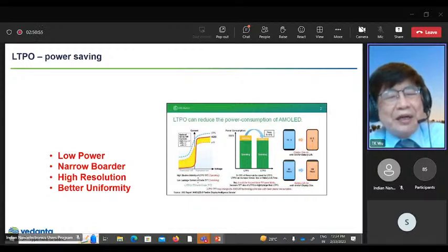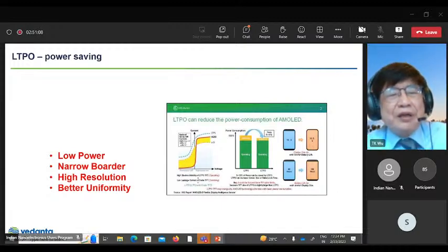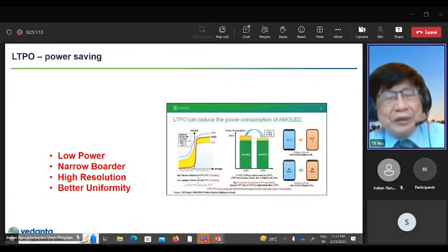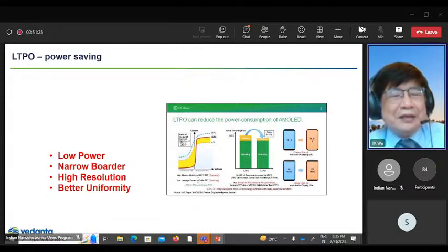At the standard frame rate, like 60 hertz or 120 hertz, every switch we charge and discharge the pixel, and it consumes electricity. But if we have a static picture on your screen, we don't have to switch the panel at such a frequency. For example, just 2 hertz. Compared to 60 hertz, we can save a certain amount of electricity.